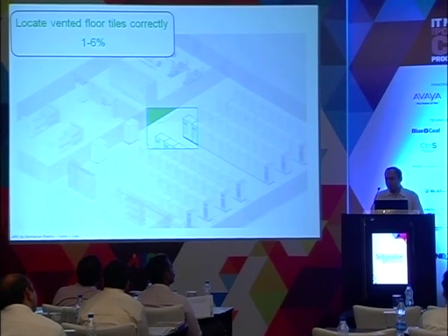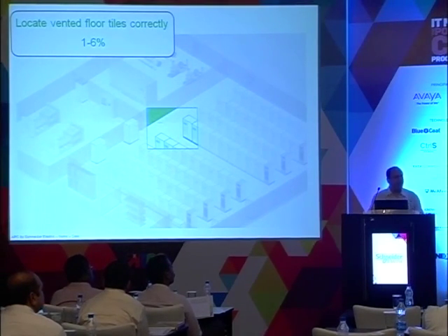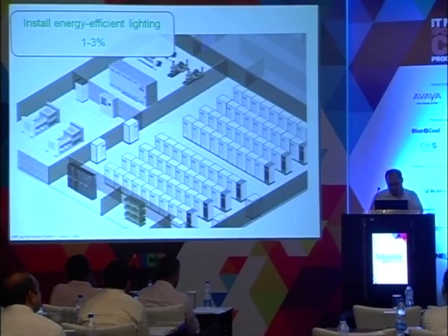Tiles placement. Many times I have seen even hotels having tiles, right? So we need to bring in a discipline where we identify and accept the fact that in a data center there will be some region which is expected to be cold and some region which is expected to be hot, which is the backside of the racks, right? By not doing that, we are unnecessarily mixing hot and cold air, which is again going to hit us in the reduction of overall efficiency of our data center.